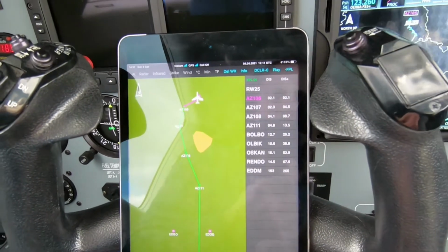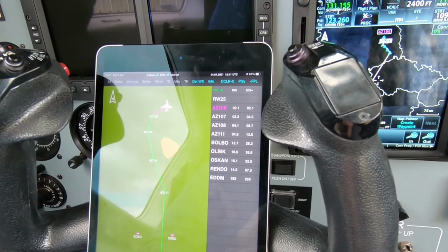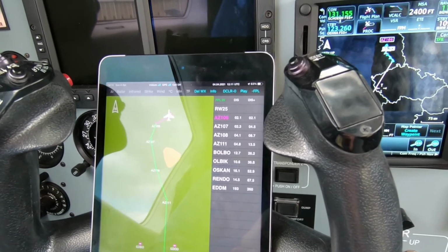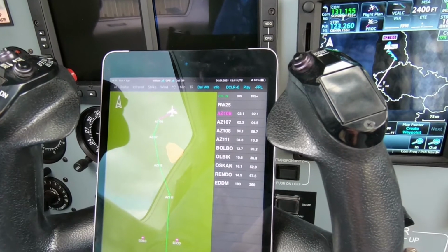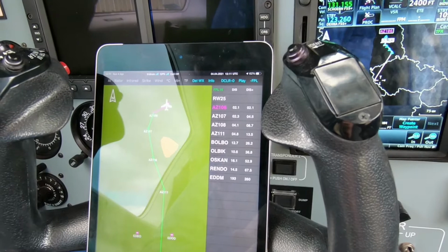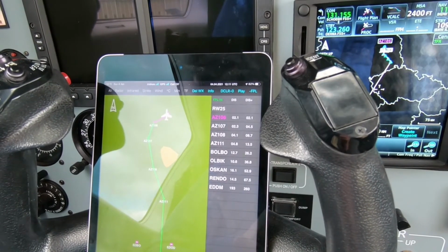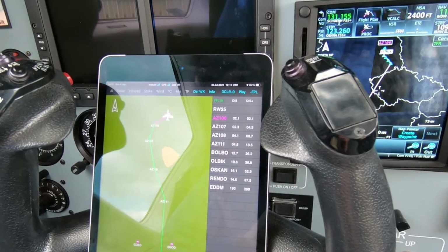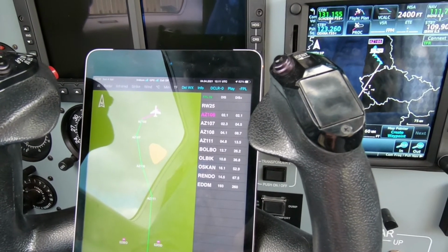And so this is a very convenient feature, because this way you no longer have to enter any waypoints on the ADL system. You automatically get the waypoints you entered in your GTN 750, or this works the same for 650, for GNS 430, 530, IFD 540, 440 devices, and some other GPS navigators. And then you can download the weather according to the corridor.